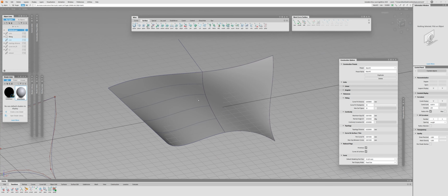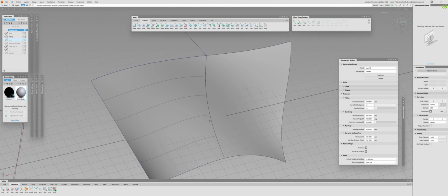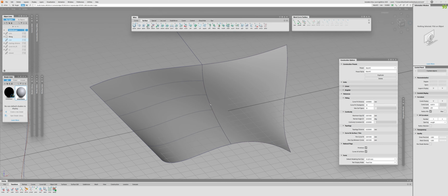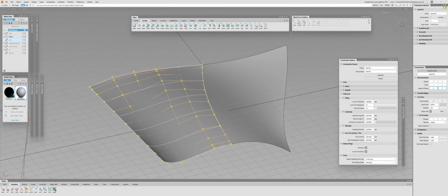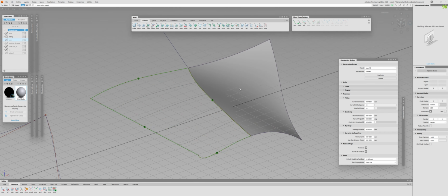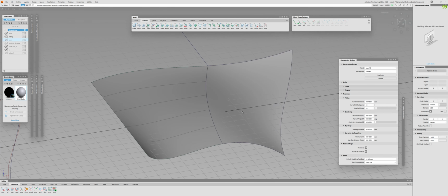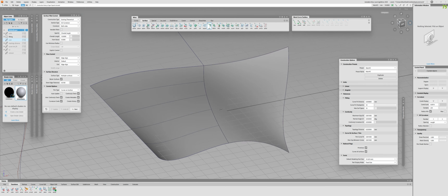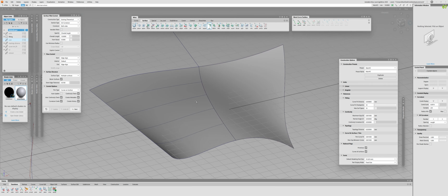And on top of that, talk about the curve fit distance as well. So I'm going to have this surface. I will just delete this and recreate it, but this time to position. Right. And now what I'm going to do is create the fillet between the two. Now I'll use the fillet tool, and I will decrease. No, actually leave it like this, 10.